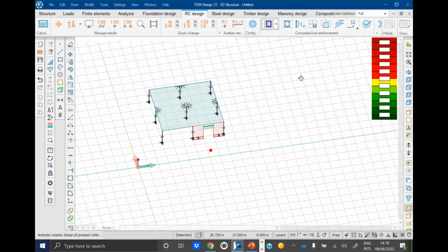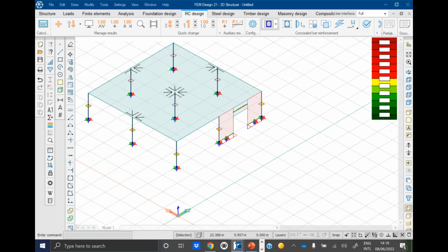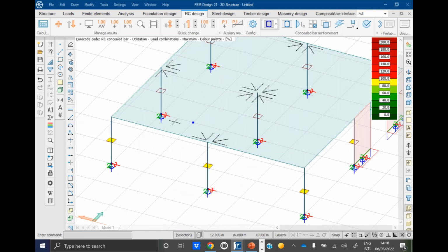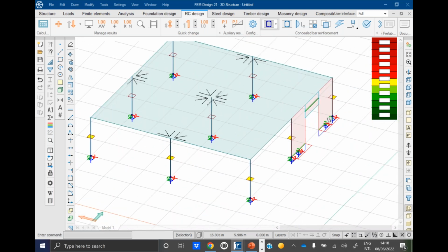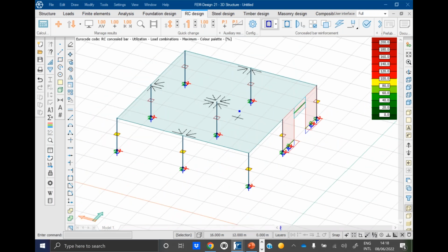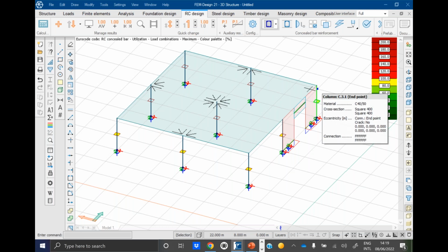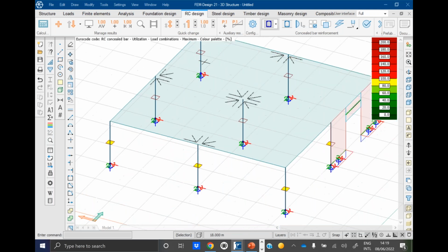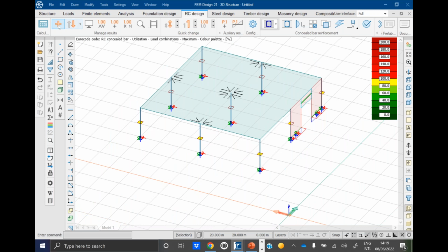Okay, this concealed bar has other uses as well, depending on the project and the wall part. If you want to design a deep beam, you can use it, design it initially as a wall, and then use this concealed bar function, and then you basically have a deep beam. Okay, then yeah, let's move to our beam and column.